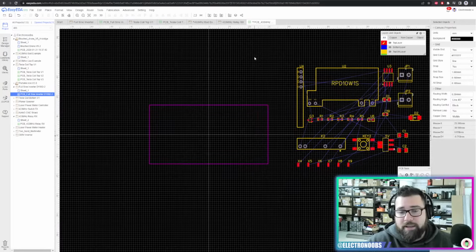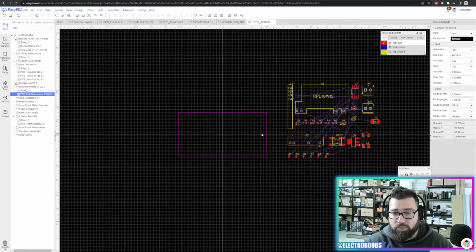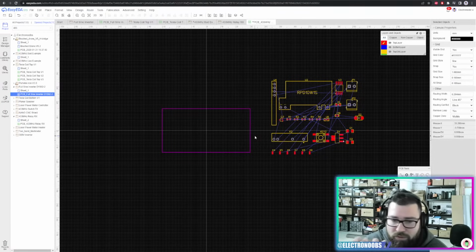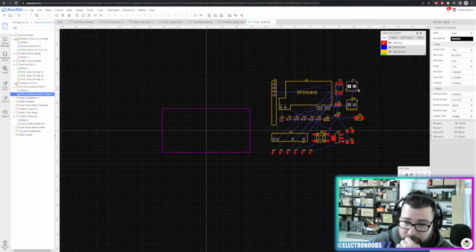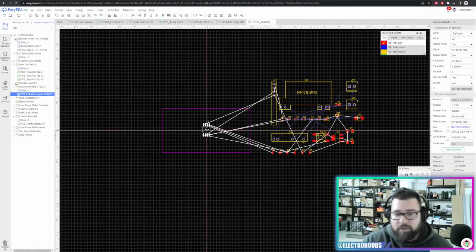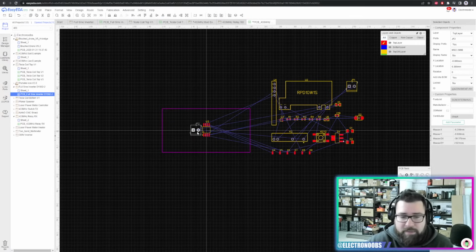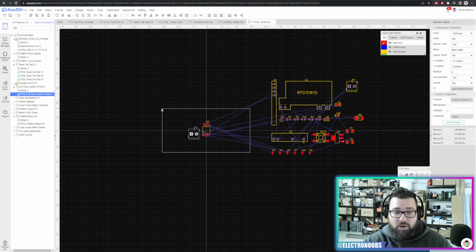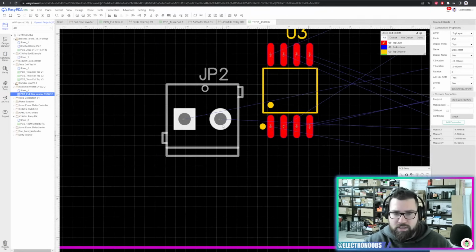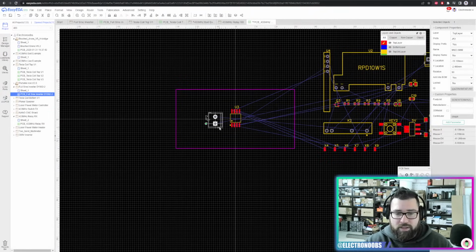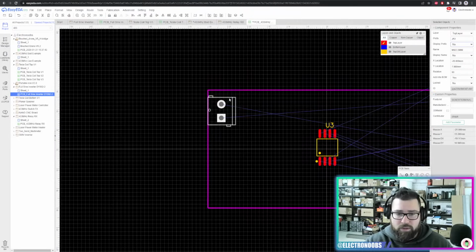Okay, so let's just start. The first thing that I do once I have my PCB, I decide where to place the components. Obviously, I will have an input and then the controller output. Usually when you have a microcontroller, you will want to place the microcontroller as center as possible. So this will be something around here. And then you have the connectors on the outside. You don't want to place a connector in the middle of the PCB. That's not very clever. So usually the connectors will be on the perimeter of the PCB. So this is the input connector, yes. Let's just say that I will place it right here, and I will hide the prefix because I don't want to see it.